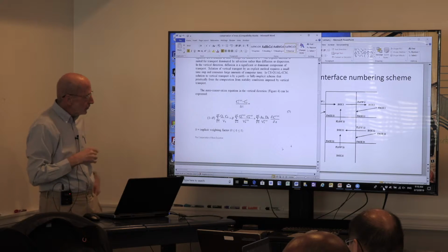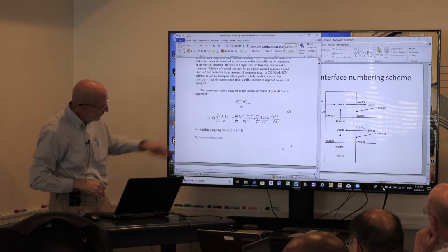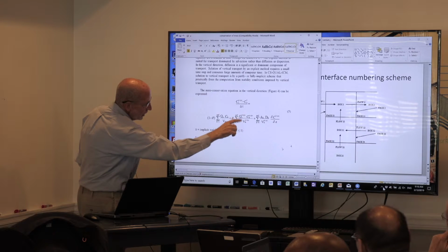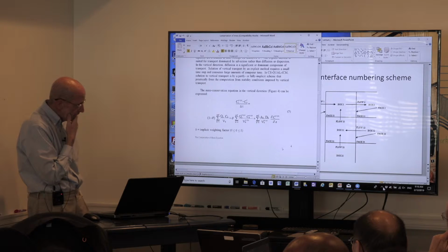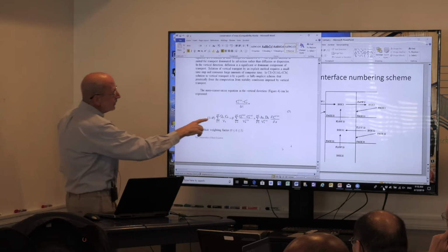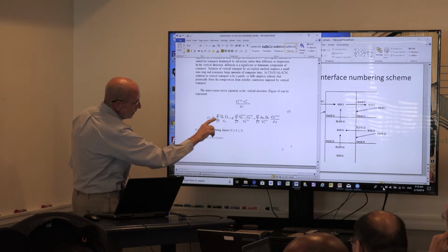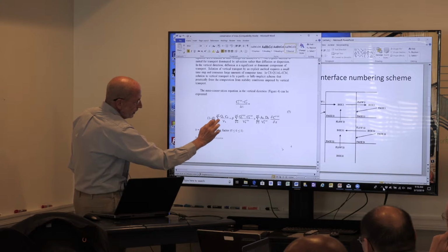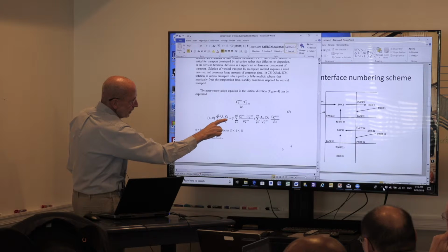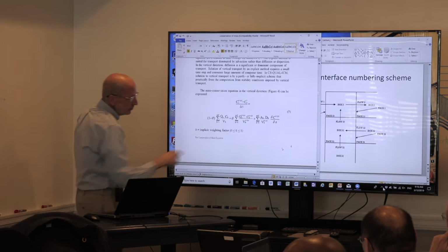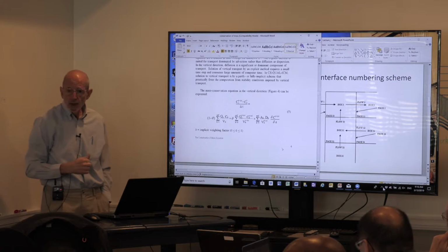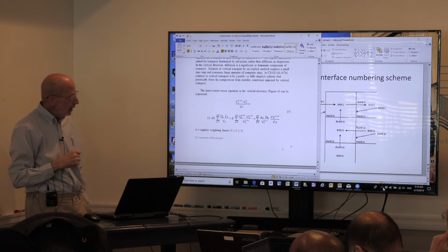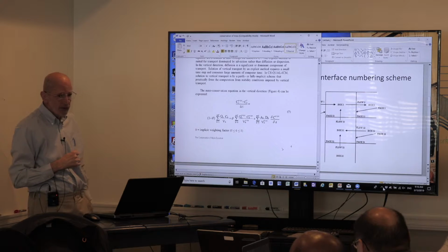So what we do here is you see that this is flow times concentration divided by volume. So that's a change in mass, a change in concentration. We've got this thing theta. And you'll see that what we're saying is that the change in concentration here is something based on the concentration at the present time and something on the concentration at the future time step. So what we're really doing is interpolating between those two times. And I won't go into all the details of this right now.